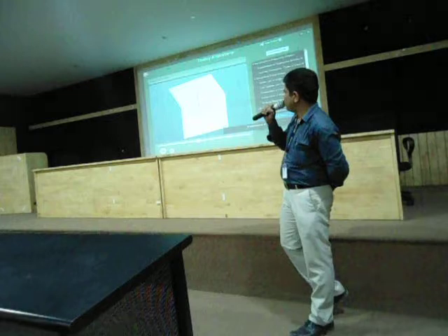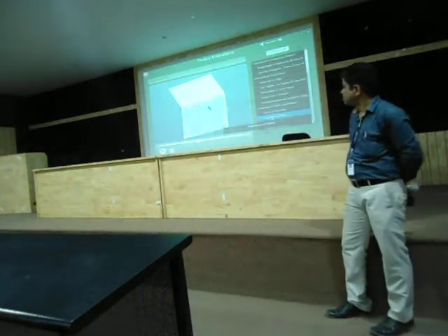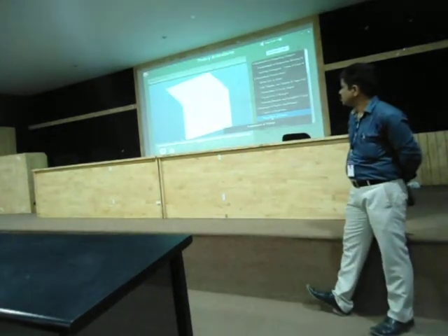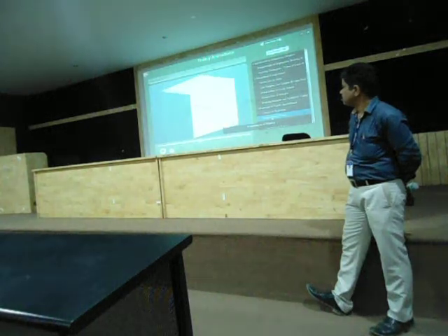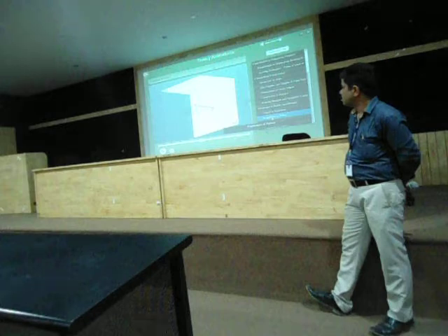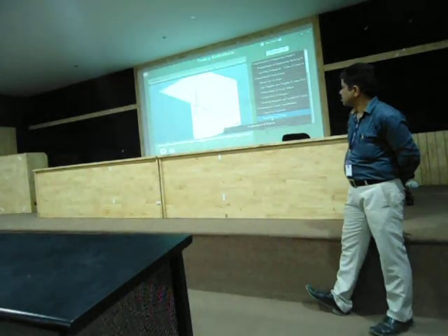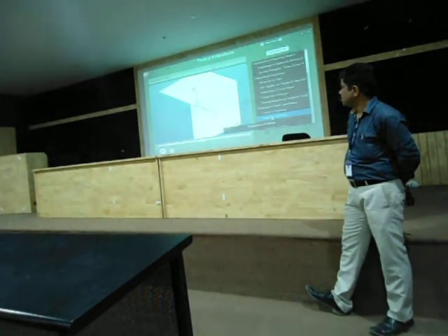is the projector. Now consider a point object in the third quadrant, below HP and behind VP. Then the front view will be a point A dash on VP, and its top view will be a point A on HP.